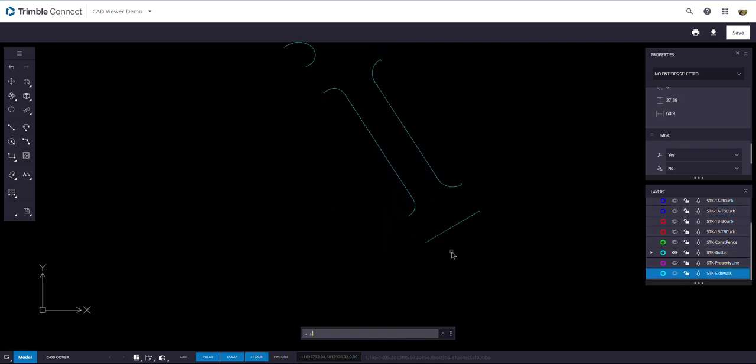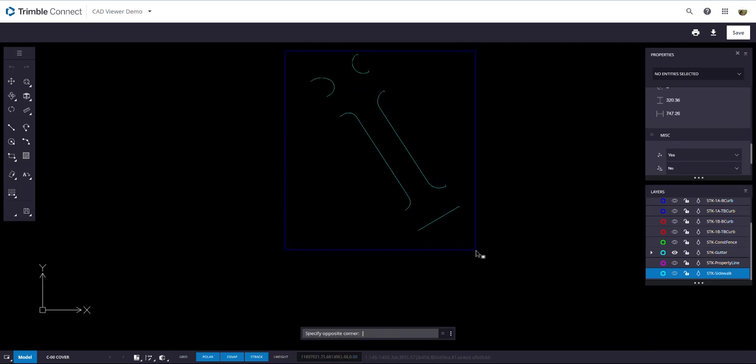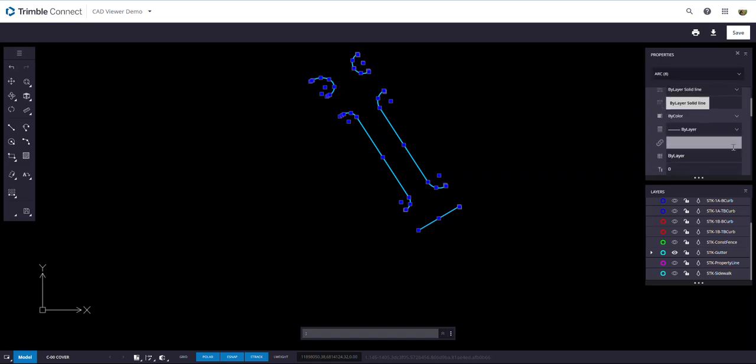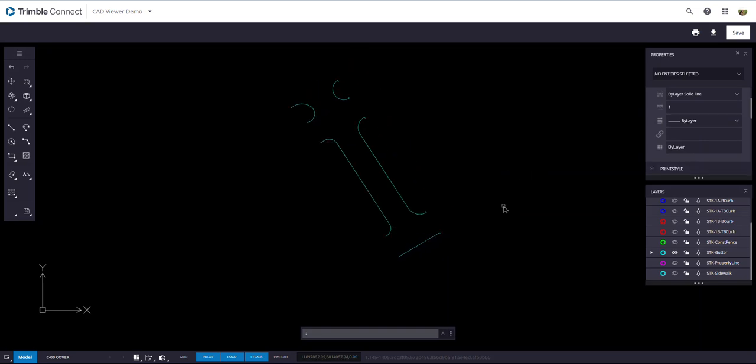We're going to do the P edit. Actually, let's select them all first. And this is just a little bit quicker way of doing it. We got arcs and lines. So again, we're going to set the geometry so that they're all at 0. And we'll do the lines, and we'll set them. We could make those polylines, but we're going to set the ends of the Z value to 0. And now we can do the P edit.